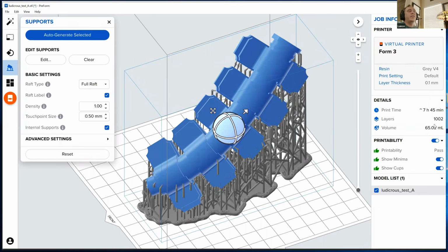It's going to take 1,002 layer slices, and it's going to take approximately 7 hours and 45 minutes with Formlabs Gray V4. Okay, this is incredible because it's actually incredibly accurate. It gives me an ability to start budgeting not only my time, but also my amount of resin being used. Okay, I can now actually give a prediction to a client when they'd be able to have it.